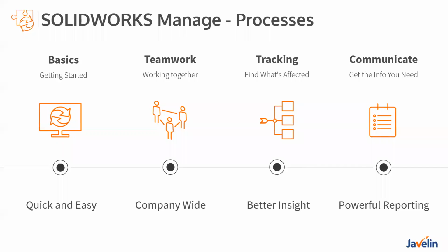There's one that says, are group users synced with PDM? And if not, are PDM user groups available in Manage? Absolutely, yes, with that integration with PDM. When you first sync up a vault, it's going to bring over all of the users and all of the groups that already exist in PDM into Manage. And if they change in PDM, they can be synced into Manage as well. So if you make changes from the PDM side, you can have that update in Manage also. And all of their securities, PDM-wise, are also respected in Manage.